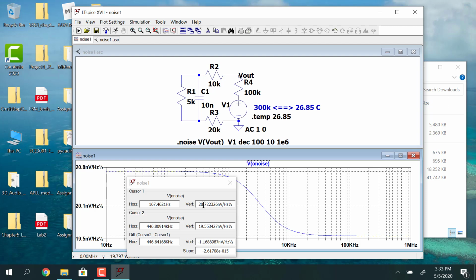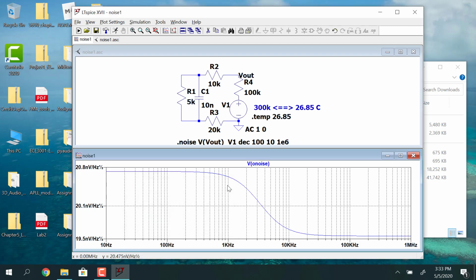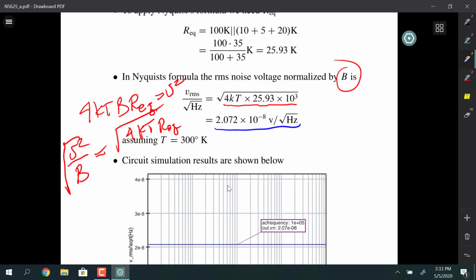And of course, if you want to do other things in SPICE with active components and things that have different types of noise generation mechanisms, then SPICE will take care of all that for you too. I'm showing this to you because you may bump into this someday. I had never used it, but then I worked on a problem for a company called NavSys, and I helped them with a frequency synthesizer that was having some noise issues, and I ended up modeling everything in SPICE so that I could understand where the noise was coming from.